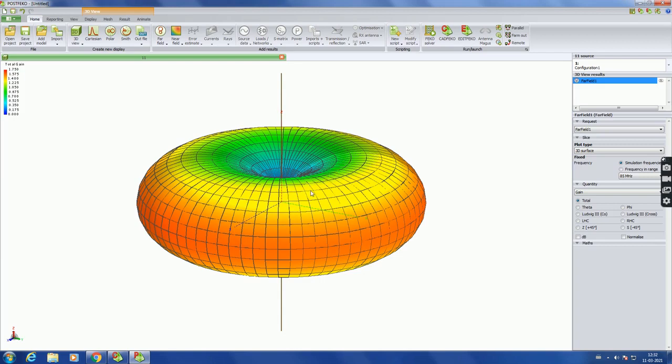So that is the definition of an omnidirectional pattern: your radiation should be even in one plane and it should not be even in another plane. You know what is the difference between isotropic pattern and omnidirectional pattern. Isotropic pattern, in the sense, in both the planes your radiation pattern should be even, so you get a perfect sphere.